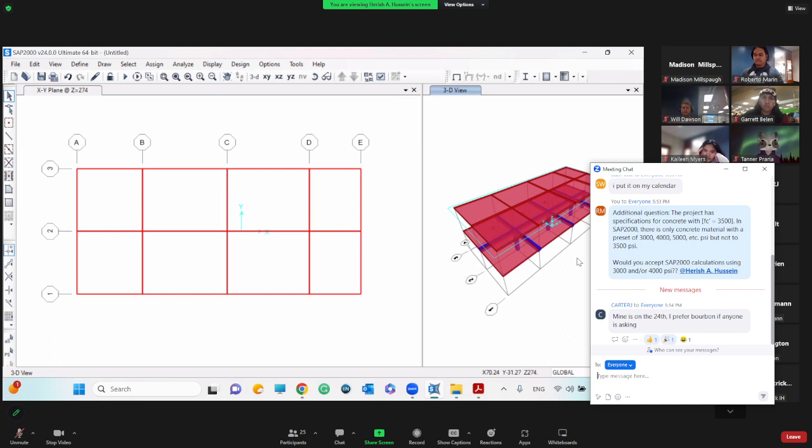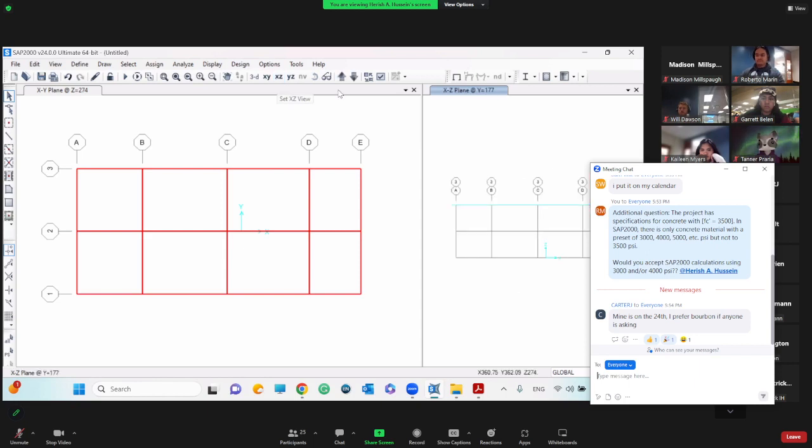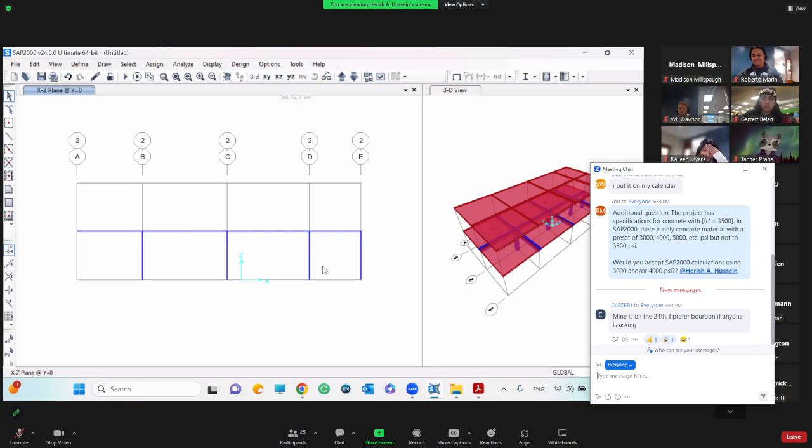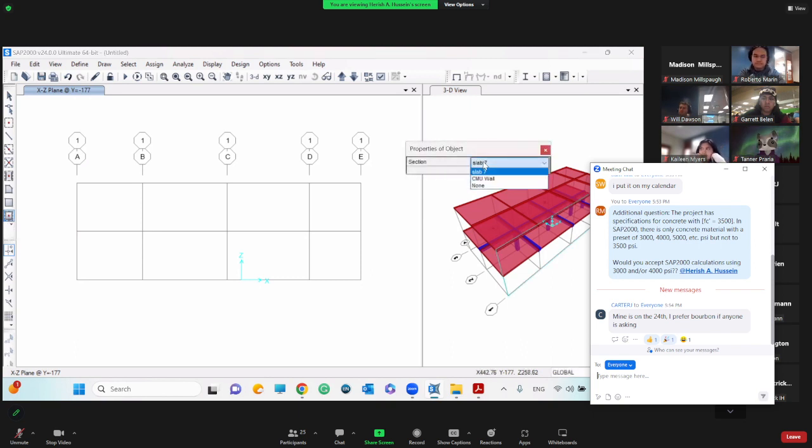When we do all around, we do this plane view, which is XZ. I work here, X for XZ. We do this panel first. So let's see where we are at. We are right in the middle. We don't do the middle yet. We do this outer panel. CMUs everywhere. Click here, just like the slab one. Pick CMU wall. 1, 2, 3, 4, 5, 6, 7, 8.